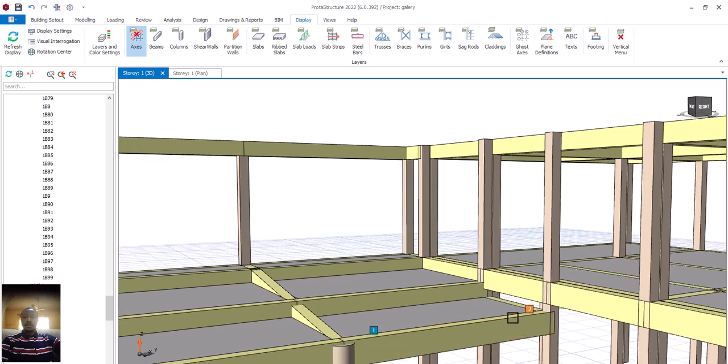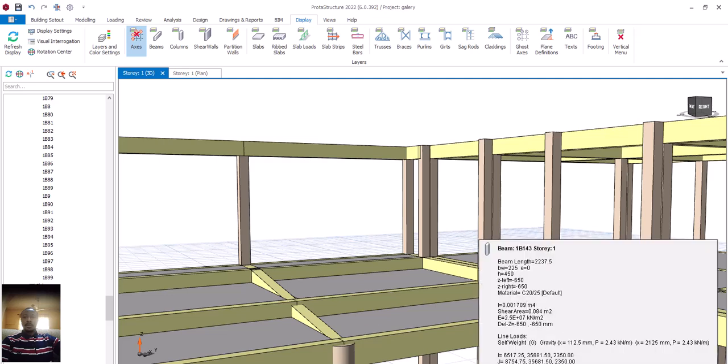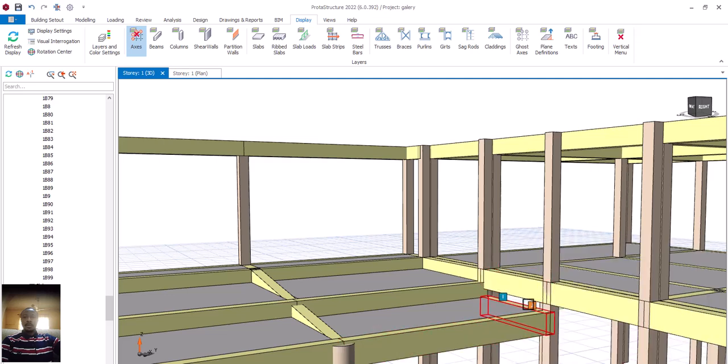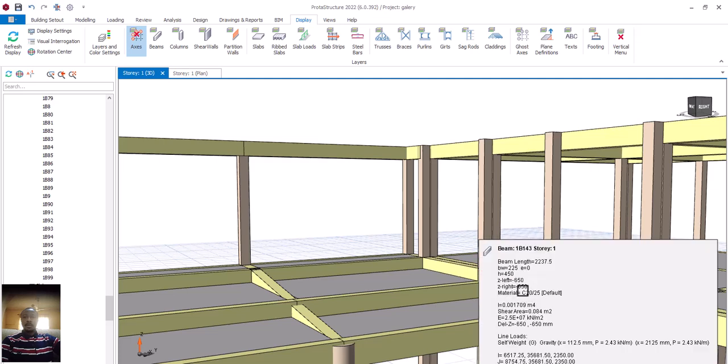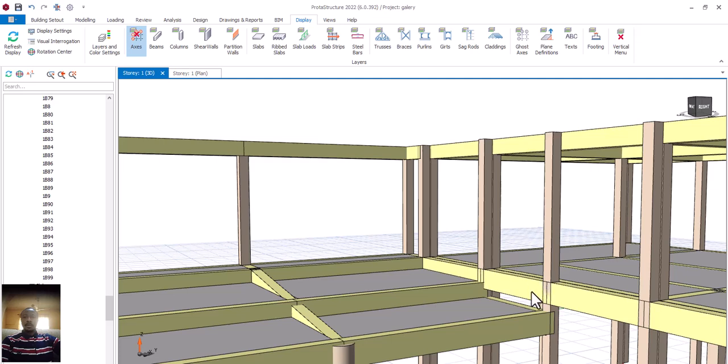What I want to show you, can you see this side now? If you look at this other side, you can see what we did here. But in between this place, they can use a block work to connect at this point. Is that okay? Instead of making this one a deep beam, to reduce cost you can just use block, because the amount of concrete you are going to use in between this place is not small. It will cost less, isn't it? To have a deep beam from here to this place is quite much.